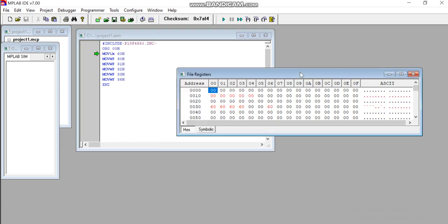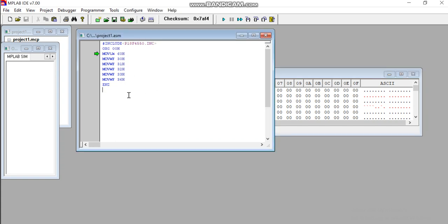You can see the memory locations, which is the 30. So this is basically 30. Fine. Then 31, 32, because this is 2. Then 3, and then 36 hex is actually storing the value of 60 hex in the memory locations. Fine. Now let's just modify a little bit